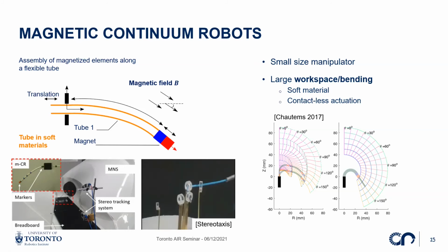They are usually limited in the number of actuatable degrees of freedom because it's difficult. We could imagine that in theory you put two different magnets at different locations and try to generate different magnetic fields at these two locations. But this is actually very challenging if you want to have a large workspace and have this huge variation of the magnetic field. With a big system like this, the field is almost homogeneous, not entirely, but homogeneous. So you just control two degrees of freedom with this.